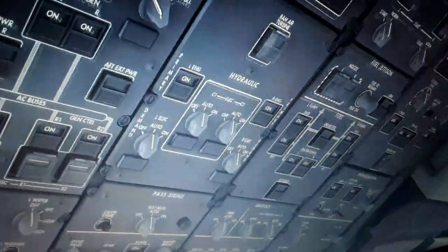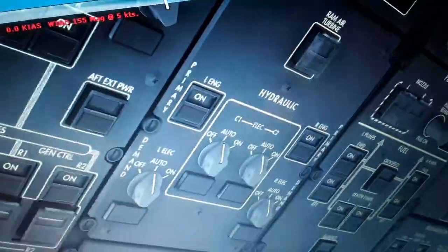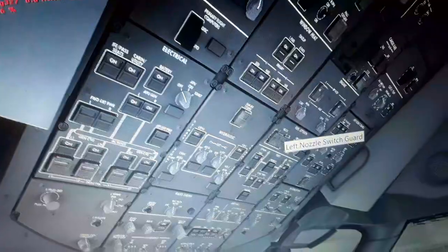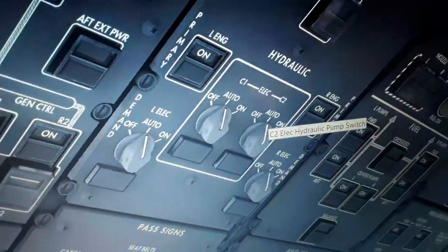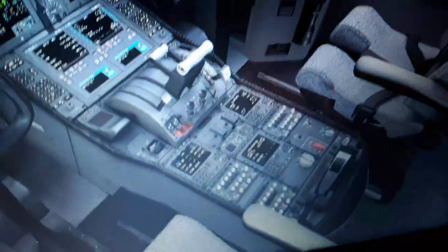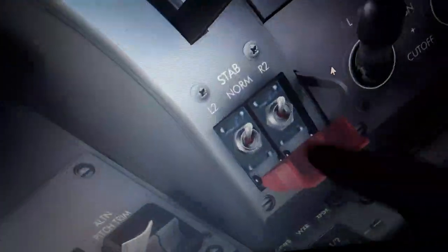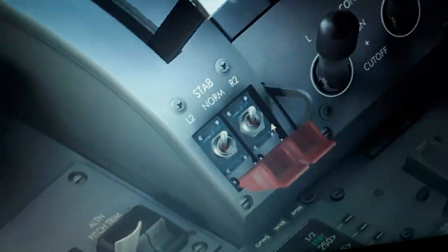So if we have a hydraulics failure, you can see the primary and the demand, engine drive and electric drive pumps, all pressurize the hydraulic fluid, which is also pressurized from the pressure from the engine. It will affect the automatic trim from the autopilot flight director system panel and the auto throttle and the flight management computers and the flight control computers. So you open up this red guarded switch for all Boeing, as I told you, 737, 747, 757, 767, 777, 787 from normal to cutoff.